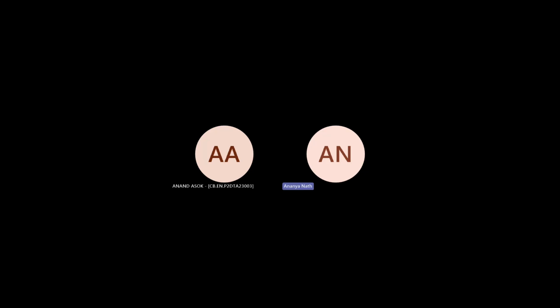For example, whether we are printing in the directed energy deposition process, the laser powder bed fusion process, or fused deposition modeling, the tool path planning will be different for different processes. Each process has a different layer history. By layer history I mean the thermal history and the tool path, like how the tool will move, because each tool will be different for different processes.